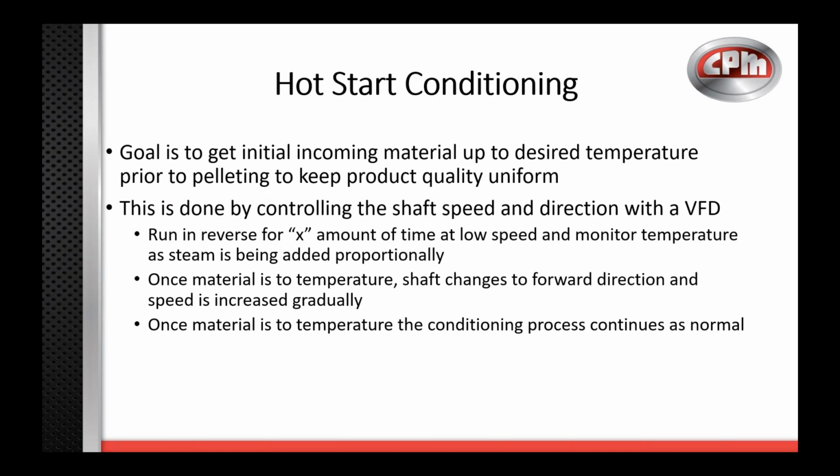Okay, so we're actually going to change gears here a little bit, and we're going to switch to talk about hot start conditioning. For hot starts, the goal is to get the initial incoming material up to a certain temperature prior to it being pelleted to keep product uniformity from start to finish. So you're essentially eliminating the ramp up time where the temperature is gradually increasing to your desired running temp.